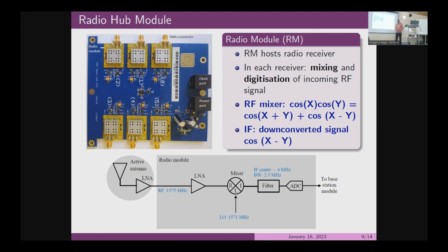Now, the beauty with this is that even for the manufacturer, you only manufacture one filter at a specific bandwidth and center frequency. So if you need a different signal here, you just tune the oscillator, right? It's easier to tune the oscillator, and what comes out, you just use a single filter. And then after that, you change the analog signal to a digital signal, and then this goes to the base station. Now, that is heterodyne technology, very powerful, that it has made wonders in radio astronomy. All right, so this is what we have here.